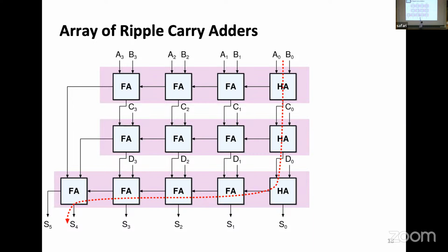And while I'm doing this, A2, B2 has already the carry propagated because it took some time until I came here. And if you look at it, if you only use ripple carry adders, if you only use full adders, and these half adders here, you will realize that the critical path actually goes through the final adder, and then this linear organization of the blocks. You remember the first addition I showed, multi-bits? That's a linear structure. At every stage, I'm adding one more, makes it very regular. And in the end, I have one carry propagation adder coming in here.